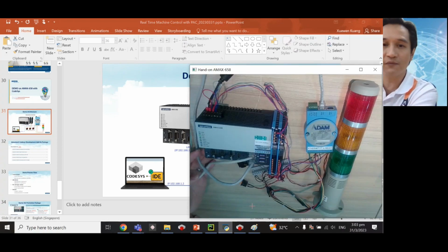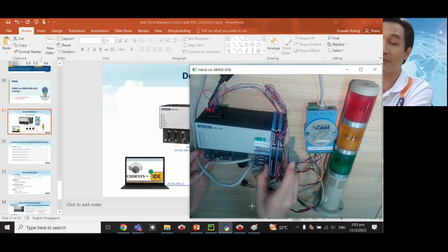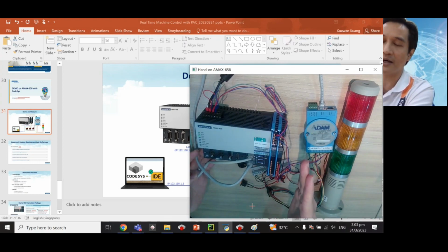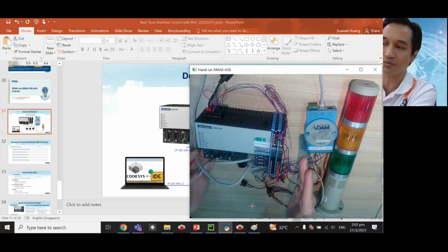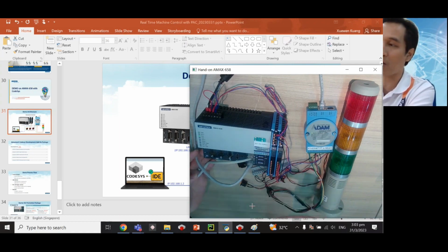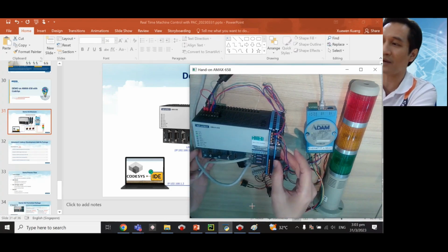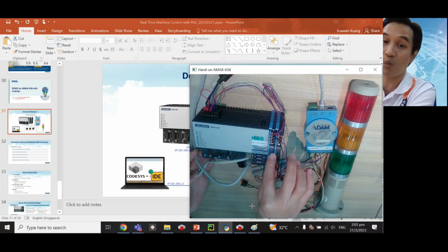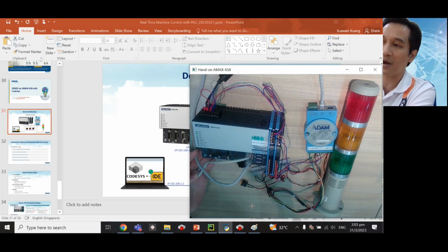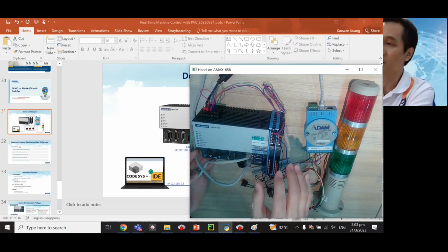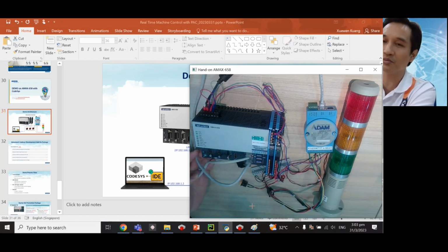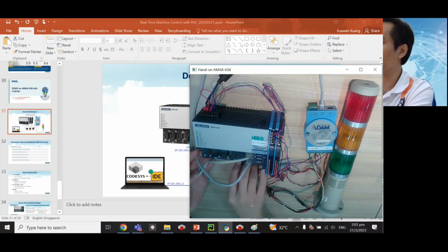If you are using a newer model, you may not need it, but you can step up to a maximum of 10 IO modules because they can only stand that kind of power consumption. If you want to use the IO module, you have to use this module, right? So 5001 first. This one has power with the IO and communication together, right? So you must use this module. So when you order or check the module, different kinds of controllers will have different kinds of combinations. You really need to take note of this part.